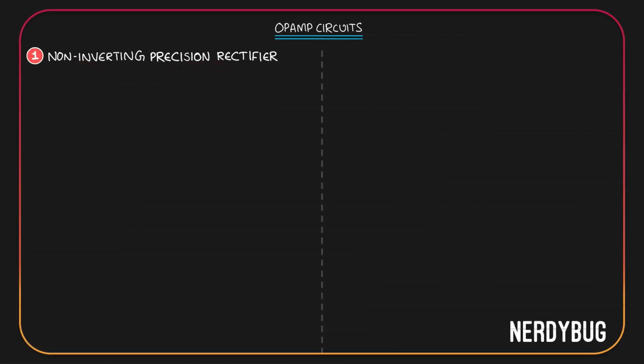Let us start with non-inverting precision rectifier. But before we get into it, let's bring in the simple rectifier that we already know. This is a half-wave rectifier. We have a practical diode of knee voltage 0.7 volt. From the direction of the diode, we can see that the circuit will pass positive half cycle and it will stop the negative half cycles. But even when the input is positive, the diode needs 0.7 volt across it for it to be on.